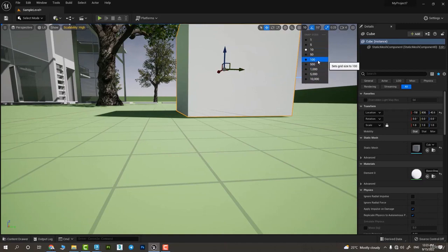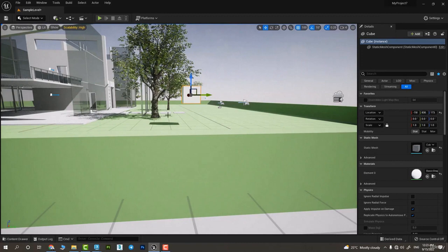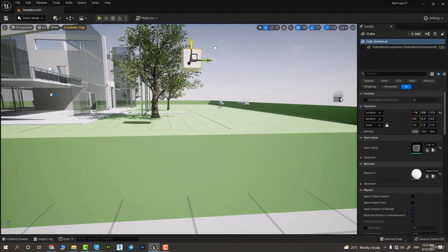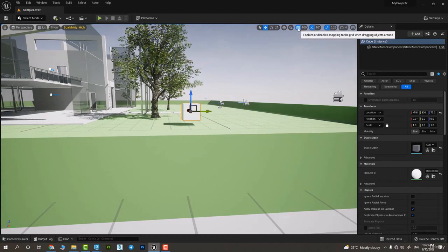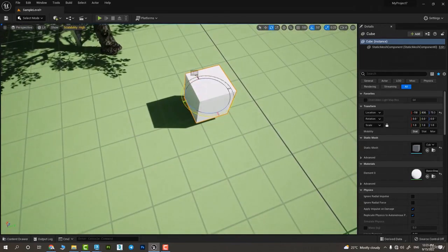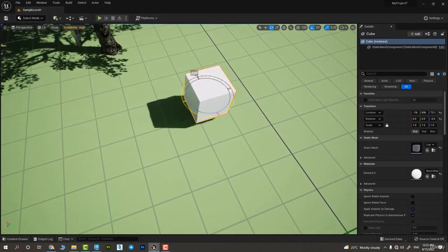And I can just change the numbers here. If I put this in 100, as I move it up or down, it's gonna jump bigger, with 100 unit increments. I think you can easily see it happening. Okay. The same concept of snap increment movements applies to rotation as well. So if I try to rotate it, you can see that it rotates in 10 unit increments.